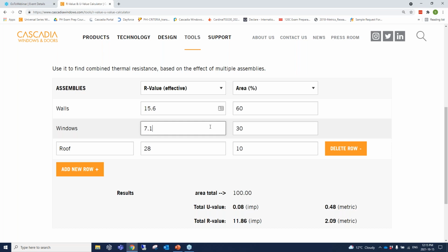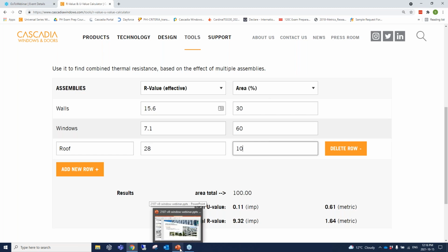This is our spare energy in our bucket. What are we going to do with it? Let's maybe make our building more valuable by switching around the glazing area to the opposite. So this is going to be a completely different looking building. We're meeting our target, increasing the value of our building, and then we can also do other things like reduce the thickness of the exterior insulation, or things like that that may be costly over the entire building. So hopefully that made sense. I'll pop back to the presentation now.